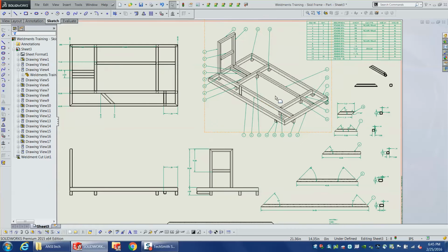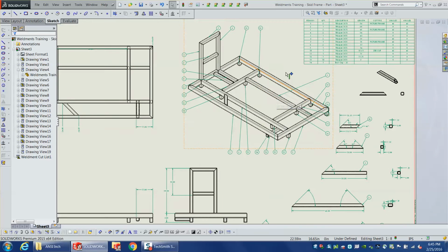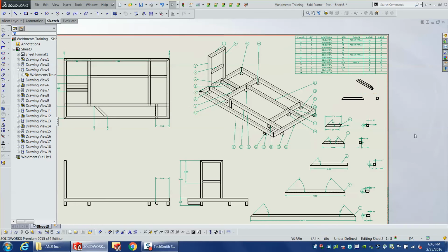One of the biggest things with this versus an assembly is, for example, if you did want to change one of those corners in here, you just simply change the corner in here, and everything is updated. Whereas in the assembly, there's two parts in there that you're going to have to go in and replace the components, create new parts for it, and make all of that type of stuff. So it's a heck of a lot more work to change something like that. I've done it both ways, but I